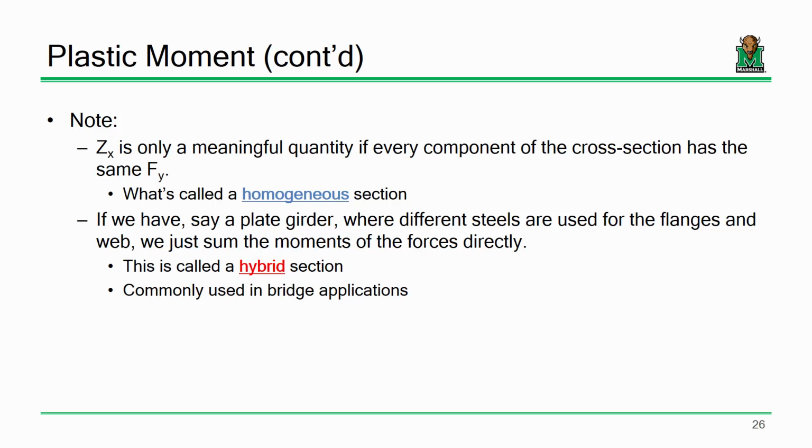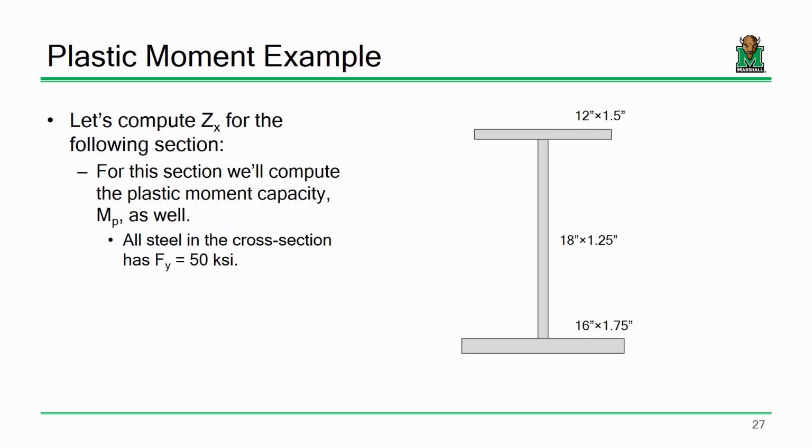The negative aspect is that if you take an I-beam and use, let's say, a higher grade steel on one of the flanges, you can take that flange and make it smaller, okay? That's great and everything. But what happens to your moment of inertia if you make a flange smaller? It goes down, right? Now, if the moment of inertia goes down, what happens to your deflections? They get larger, right? So sometimes you're perfectly fine on stress limits, but because of that damn L/800 limit in the spec, you're actually losing the benefit of that hybrid girder. I'm not saying never use them. I'm just saying be wary. All right. Sound good? All right.